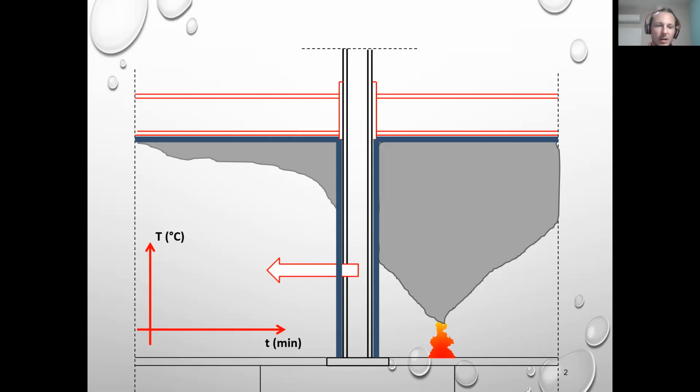If we consider a general heating curve which has a cooling phase occurring at a certain point, the first possibility is that the steel member is going to have very high heating rates induced because there isn't any fire protection present, or in the case where there is fire protection present, there's going to be a very low heating rate in that particular steel member.